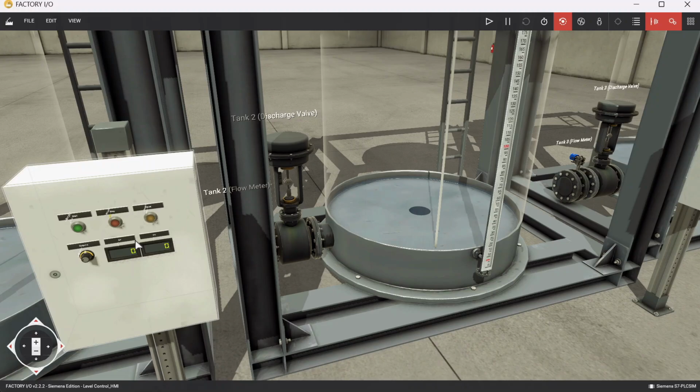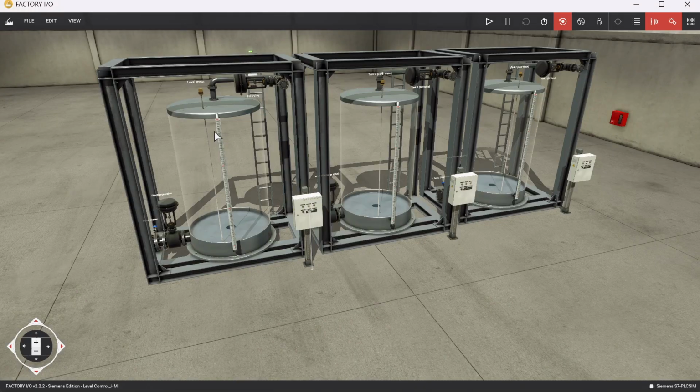So I have 3 pumps here, and something important, we have level transmitter here, or transducer: level transducer for tank 1, level transducer for tank 2, and level transducer for tank 3. That will tell us the level of oil inside the tank in real time, all right? Now, if you go to file here, you need to add your tags to their appropriate PLC addresses.